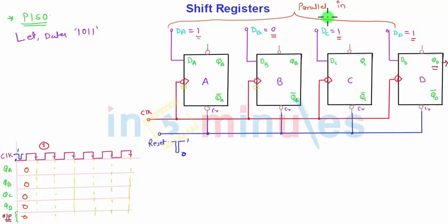So the first bit is 1 here, DD. For the very first clock cycle all the data will be fed into the registers A, B, C, D, consisting of D flip-flops. So we have 1 0 1 1. Still the output is 0, because the previous 0 is shifted out.